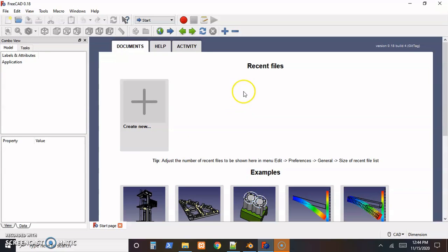And over the years, I've set up a number of scripts that'll take a mesh from Blender, which also has a nice physics engine, so we can do a lot of simulations there as well. I have scripts that will take a mesh from Blender and export it into something that can be imported into parametric modeling software, and bring them back and forth if I need to. So for right now, I'm just going to use the actual CAD software to convert that downloaded parametric solid model into a rendering mesh to work with in Blender.